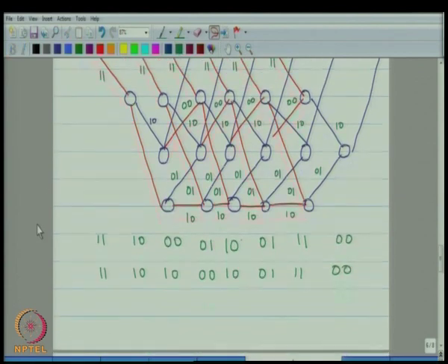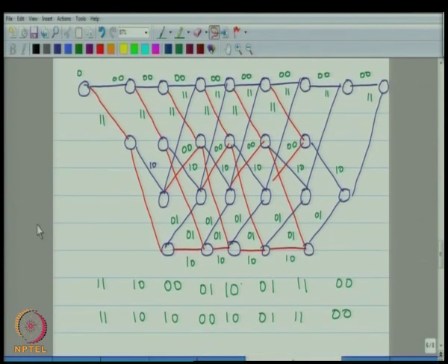Okay, here we go. And now what I want to do is, on the trellis, I want to focus on the received sequence. So I want to focus on this and mark on the trellis in place of the output sequence, the Hamming distance between the corresponding received segment and the code word.